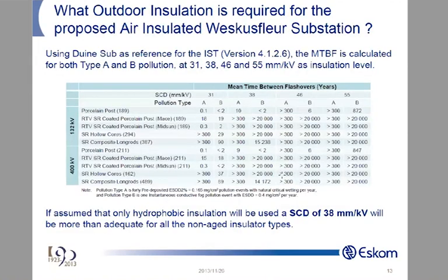And this here is how you should be using IEC 60815. The concept is to use 60815 correctly. Measure your environment, get your data. Look at your climate, get your data. Get a reference or a candidate, and get candidate insulators. Have them evaluated, get their pollution performance curves. Take the two, go in, do the stats. From there, what voltage? What line performance do you expect? And by the way, bring in life cycle costing.